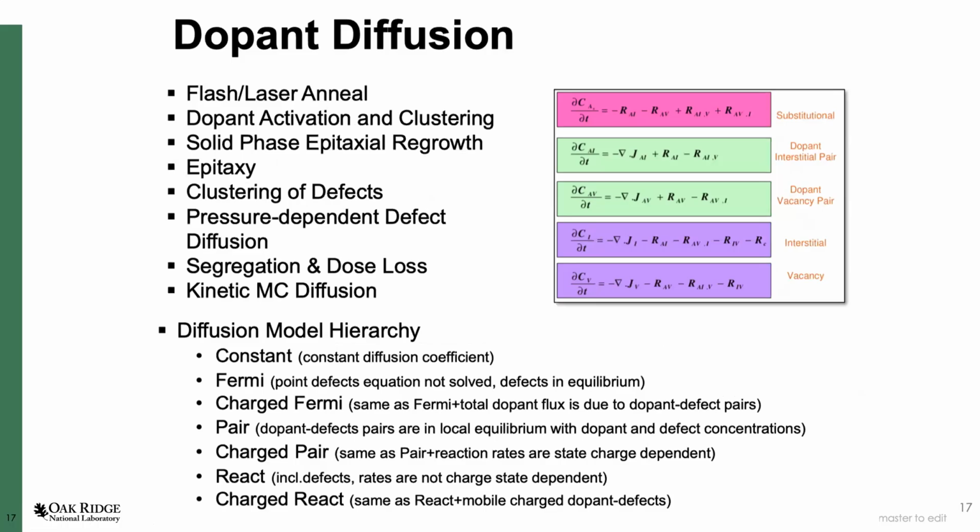Then when you add dopants in your substrate, what you're going to do usually is you're going to be heating up your substrate. That's true for CMOS detectors, and that's true for CMOS circuitry or such. You want to activate your implants, so you're going to heat up your substrate to move around these implants and defects and combine them to get the charge defects that you want, like interstitials or vacancies. And this is done usually by laser.